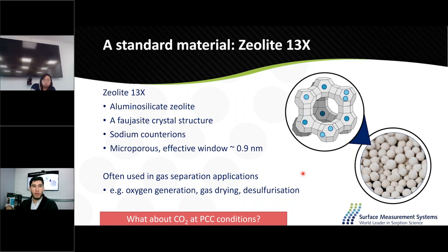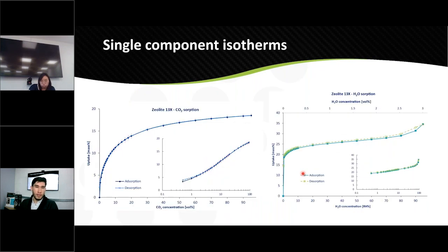In this particular study of the impact of water, we looked at more post-combustion conditions, so higher concentrations of CO2. Purely recording single component isotherms on 13X shows that it has a high uptake for CO2. That's great. That's one of the things that we want. It seems to have a good working capacity from 0 to 15%. But looking at the water isotherm, it seems that the interactions with water are also very high. So we can reasonably assume that water would displace CO2 and would take preference in co-adsorption conditions.